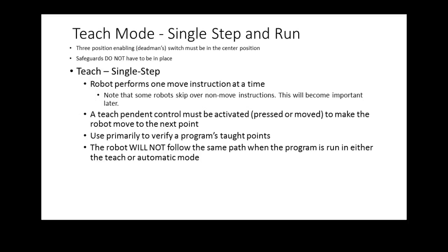But one thing we got to do, to single step in teach mode, is have the teach mode selected, right? Number 1. We got to have the 3-position enabling switch in the center position. Everybody understand that? And then every time we press a key or a sequence of keys, what's it going to do? It's going to do 1 step, and then it's going to stop.